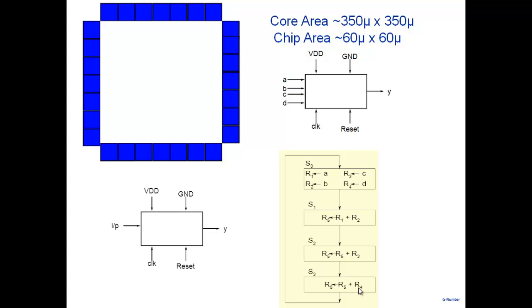So what if I think of my IC now as the same VDD, ground, clock, and reset, and I have only one 4-bit input? On the same input, I reconceptualize what my IC is going to look like, and on that I give serially now: first A, then B, then C, then D. And then accordingly you rewrite this ASM chart of how you would execute. Maybe in the first stage read A, then in the next stage read B, and then you start computing and then read C and all that. You think about how to do it here.